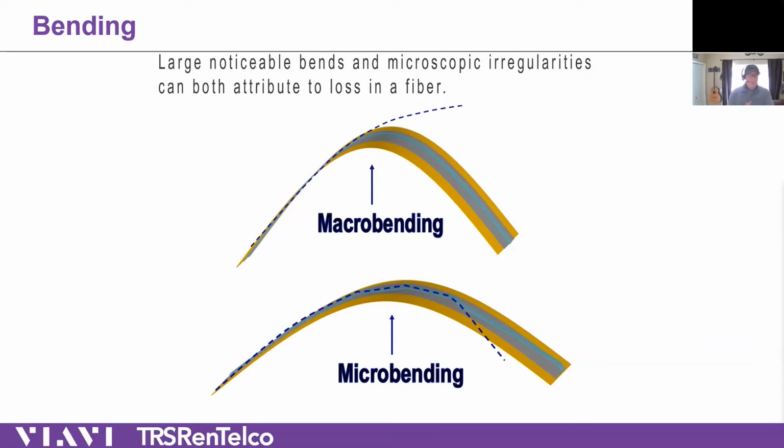But now the important stuff. What is an OTDR really good at finding? It's really good at finding connectors. It's really good at finding splices because those are very obvious events that have happened. The fiber is going and something changes. Something changes, the OTDR can figure that out. And based on what change, we can figure out, is it a splice? Is it a good splice or a bad splice? Is it a connector, good or bad? Even types of connectors within reason.